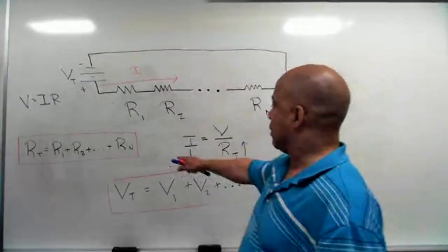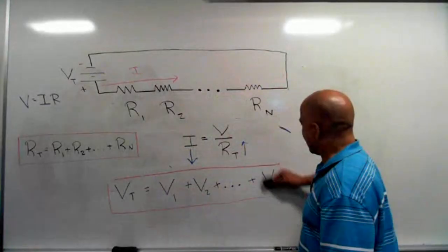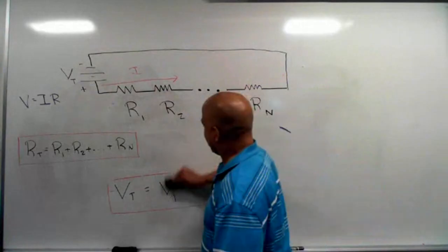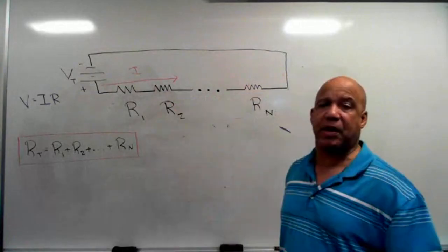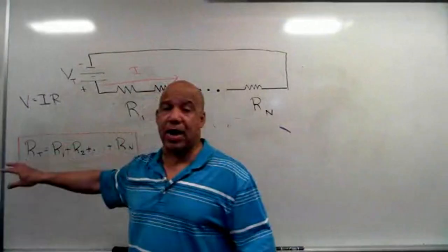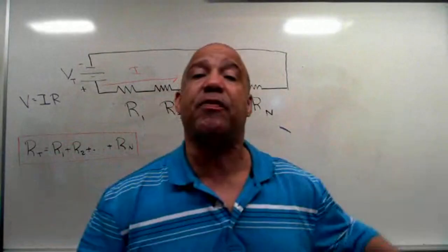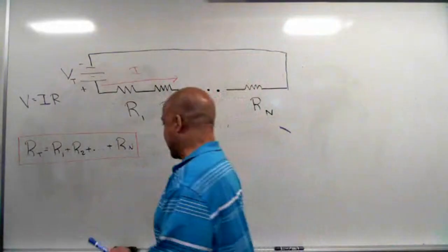So the resistance formula. And then there's this one that says that in a series circuit, if I have current flowing through resistors, then each resistor is going to develop a voltage drop. And I learned from just multiplying both sides of that equation by current that the sum of those voltage drops has got to equal the total voltage. And so we wrote that like this.